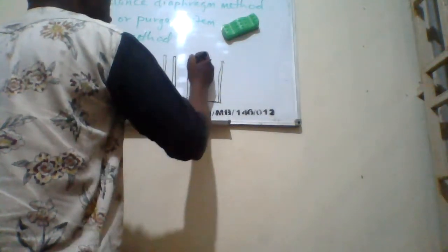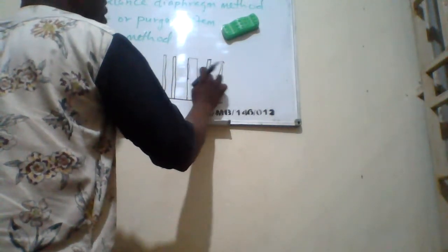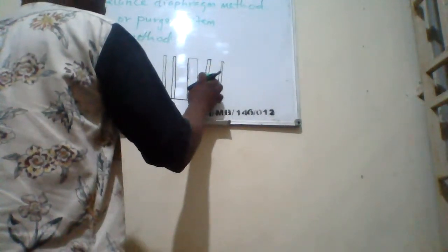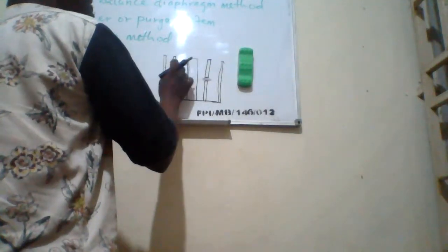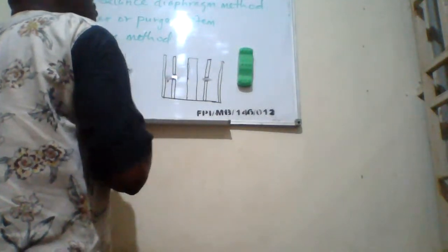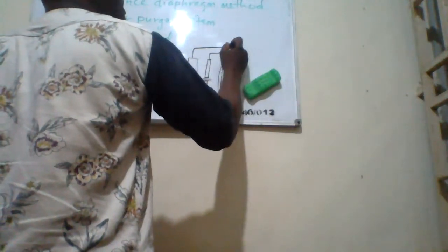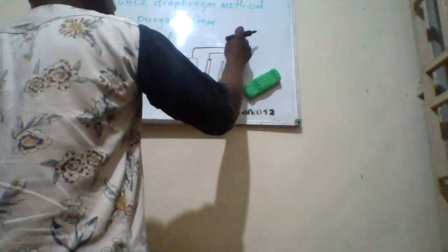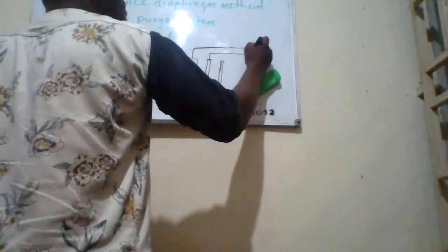But the system is designed such that the smaller tank has an opening or openings, many openings, whereby there will be passage of the fluid into the bigger tank. All right? There will be passage of the fluid into the bigger tank. Now, a high frequency electric signal is connected like this, such that if you measure between these two wires, then you will see we obtain a capacitance.